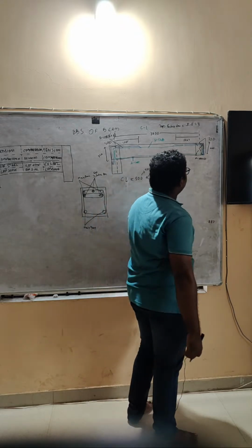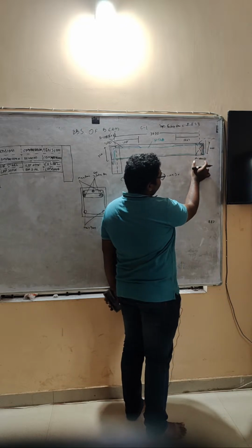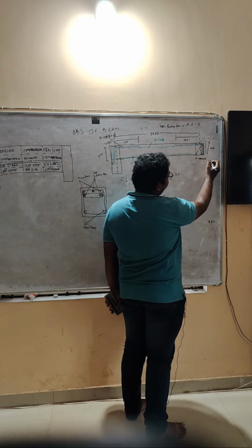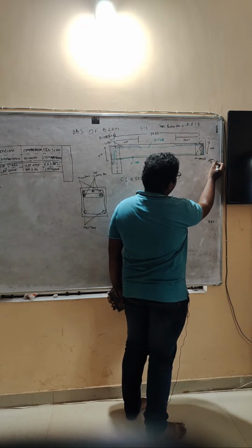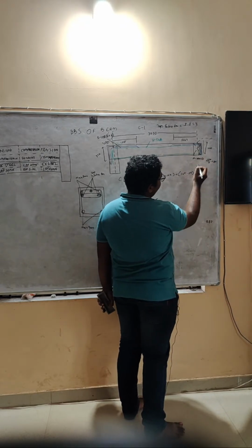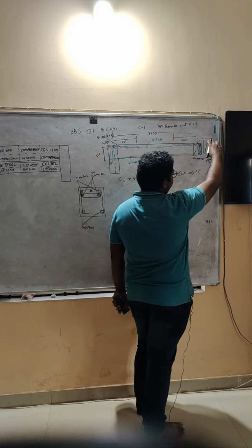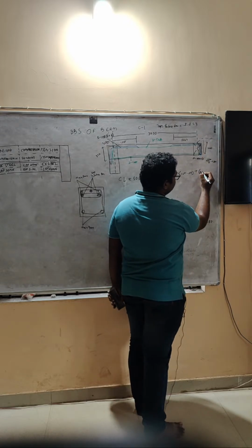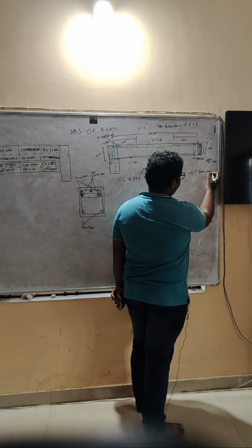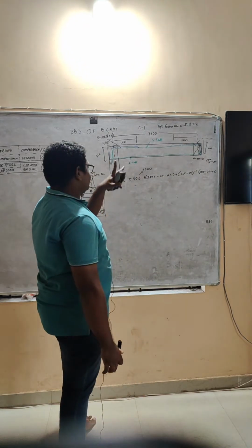Now you will notice a difference here. We will not take an LD here. You can see the width of our beam is 250, so we will divide it by 2, that is 125, and subtract 25, which is our cover. Then we will add the depth of our beam, that is 300, and subtract the top and bottom covers, 25 and 25. Then we will subtract the bend deduction for 2 bends.